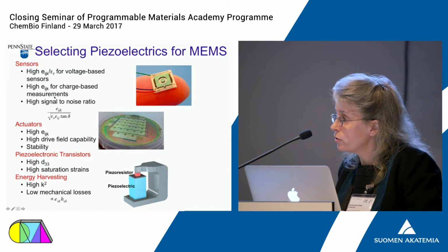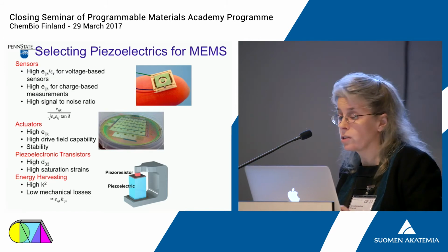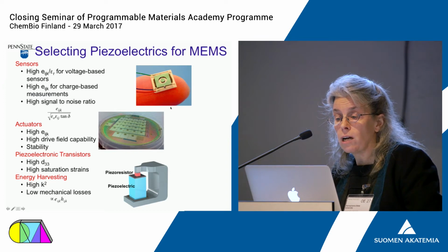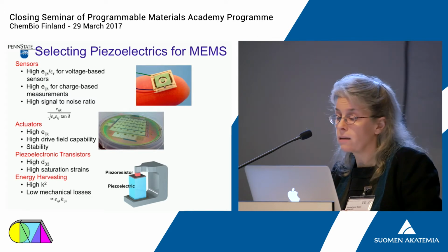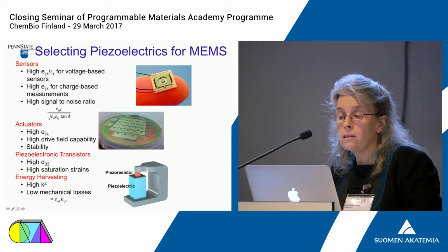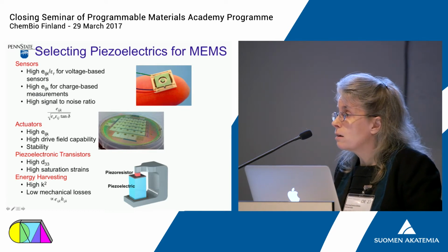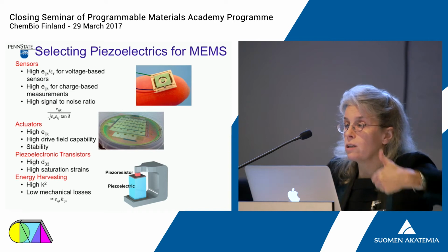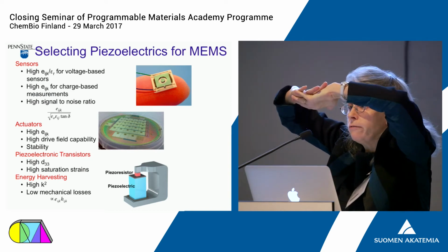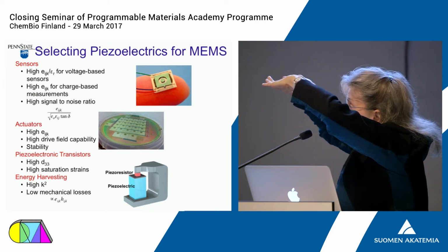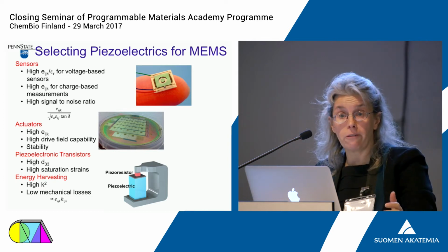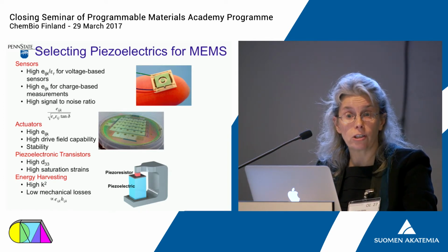There is considerable interest in being able to make sensitive sensors or accelerometers. I show here an accelerometer on a fingertip. This is about 7 millimeters on a side, had about 7 microns of a lead zirconate titanate film on the back side of this silicon wafer. And you can see the silicon wafer has been machined using deep reactive ion etching to make a thinned area. Now, if I undergo an acceleration in this direction, the thinned area flexes, and as it flexes, it bends the piezoelectric material, which puts a stress on it, and hence I can make a very, very sensitive measure of acceleration.